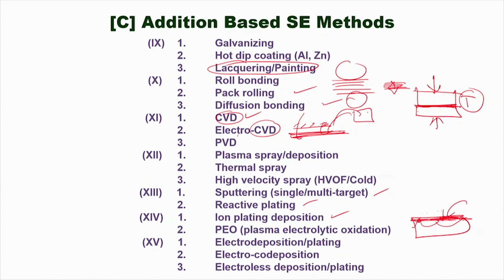Normally, when you deposit by, let's say, thermal spray or plasma spray, a thick coating of oxide layer on top, compositionally and structurally it is so different from the substrate that this interface is always a question, always a suspect. Whereas, when you oxidize the surface and allow oxides to grow from the bottom, the compatibility is much better.